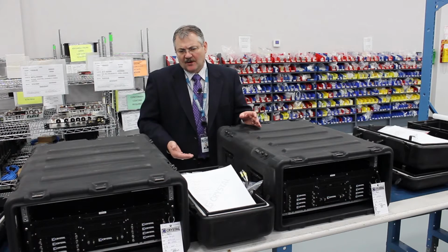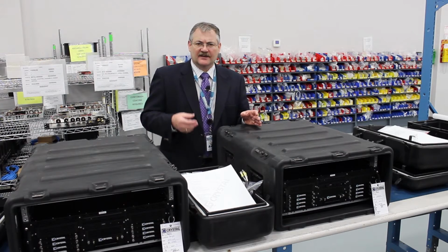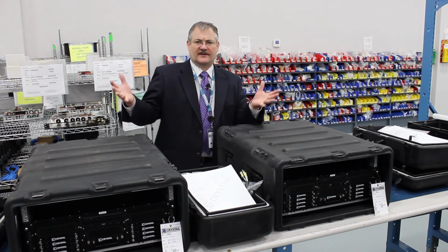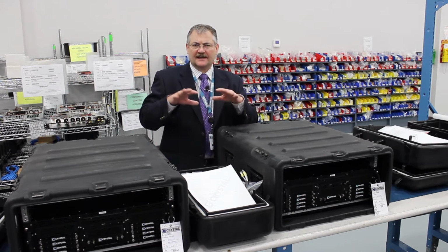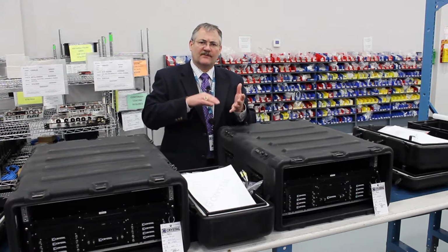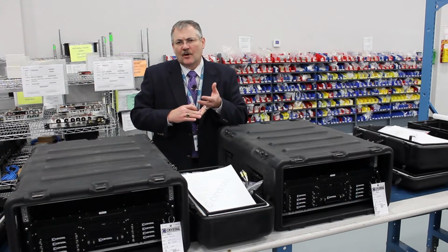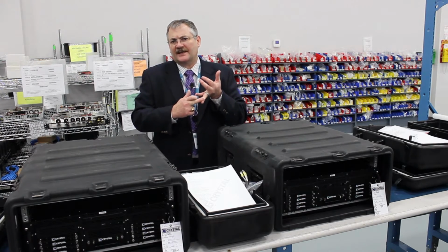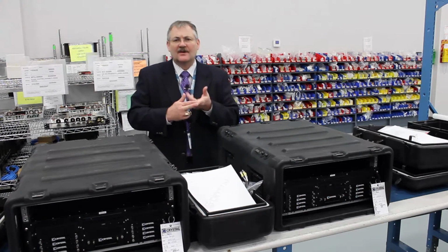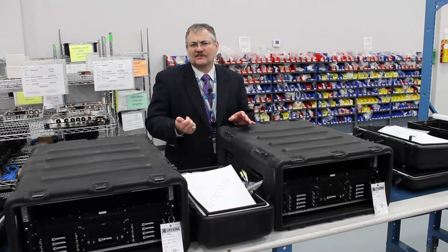And so what is it that you're looking for when you're doing this kind of testing? These are essentially surface types of tests, so you're looking at things that are more on the outside of the units. You're looking for shattered glass, or thermal coefficient of expansion changes that deform materials, crack materials, damage insulators, or alter the performance of the electrical system.